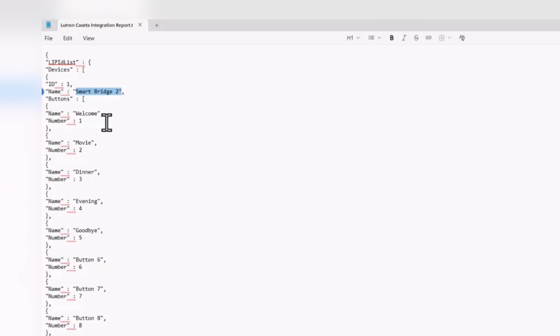Now, you can also create phantom scenes on the Smart Hub. What are phantom scenes? Why do we need them? Why do we create them? Well, phantom scenes are scenes that you create on the Lutron side, and you could run them from a control system. The reason why that benefits you is that all the lighting circuits, let's say a chandelier or sconces or ceiling lights, they all start to ramp at the same time. That's called a smooth transition instead of a popcorn effect where they're staggered out. So phantom scenes are always going to be in your benefit.